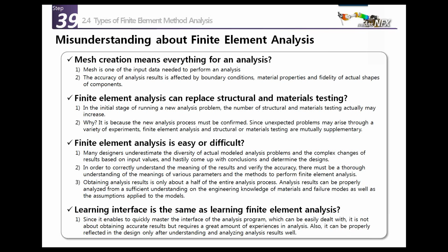So you cannot be sure that the simulation will give you the expected result if you don't have a result from simulation to compare with it. So it's important to do some testing, and once the process is well defined, then the finite element will give you a very huge potential, and also you have to spend a bit much less money on the actual real testing.